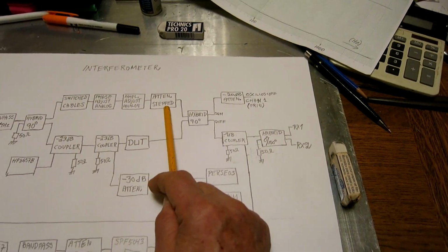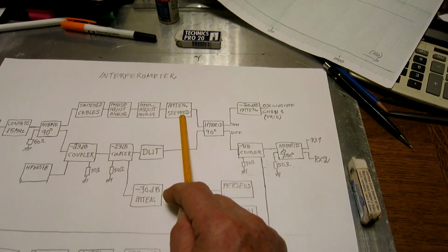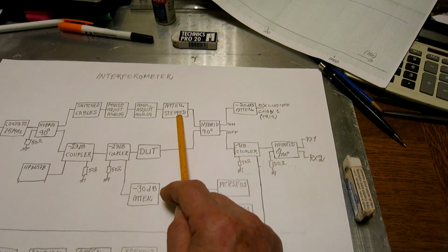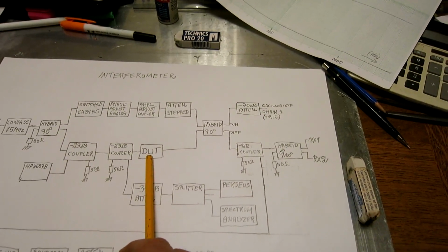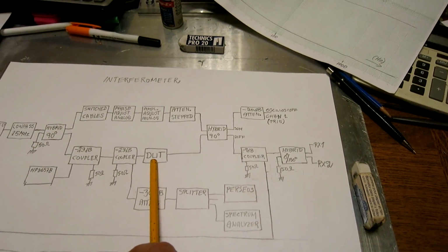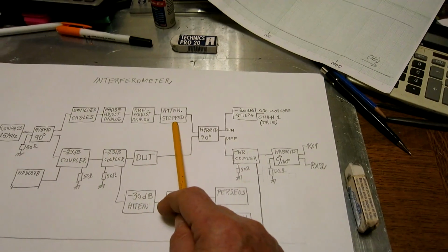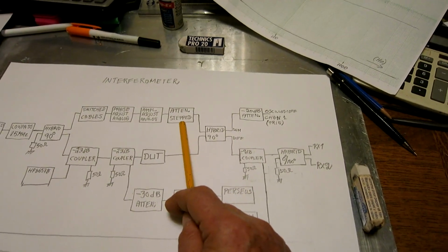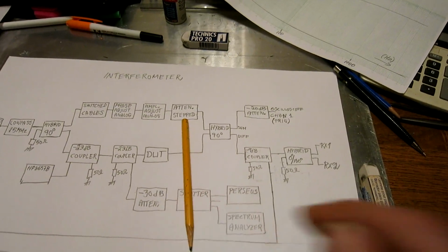And here is a stepped attenuator in 1 dB steps. And I have verified it by having a 1 dB attenuator as the DUT, and that 1 dB was a long cable, so I know that one was not noisy. So this one attenuator is okay for flicker noise, at least in the 1 dB position.